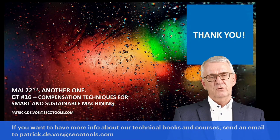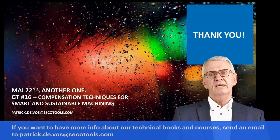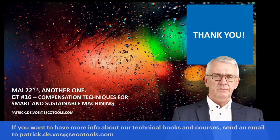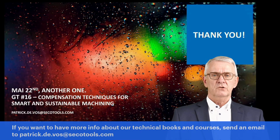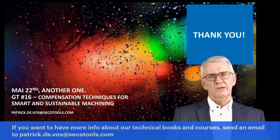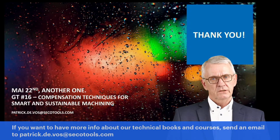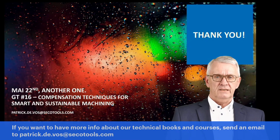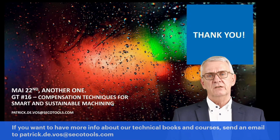Thermodynamics. Machining is the formation of material. Where material is deformed, heat is generated. Heat shows a tendency to spread out in case of a machining application. It spreads out in the cutting edge, in the workpiece material, in the chip. Too much heat that spreads out in a cutting tool I do not like, because it leads to rather high temperature gradients. And high temperature gradients give me always the risk that thermal cracks appear, and thermal cracks weaken cutting edges. Leads to premature breakage, leads to crashing of a cutting tool, leads to destroyed workpieces, standstill of a machine, and so on.